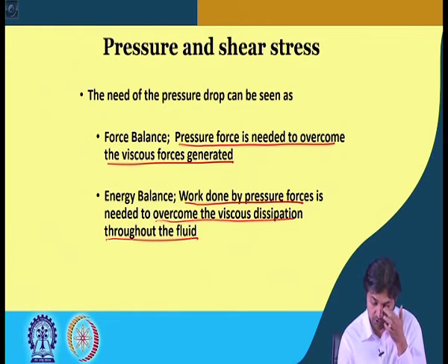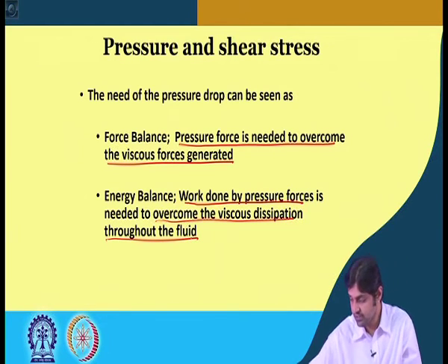So these are the two different ways of seeing the need of the pressure drop in the fully developed area, and the same can also be applied for an entrance region, just that instead of only viscous forces, it will be viscous forces plus the acceleration.